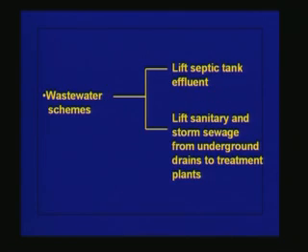So, we have to get over these frictional losses and we need to have pumping for transporting water through treatment plants. Pumping is required in wastewater schemes also to lift septic tank effluent from a lower elevation to a higher elevation. Many times we have to lift sanitary and storm sewerage from underground drains to treatment plants which are above the ground. In sewerage systems, we also need to lift water from a lower elevation to higher elevation if the drain slope is much higher than the slope of the prevailing ground.